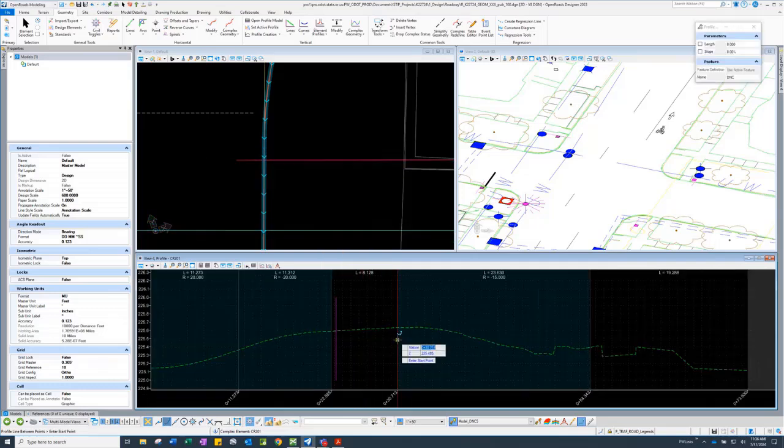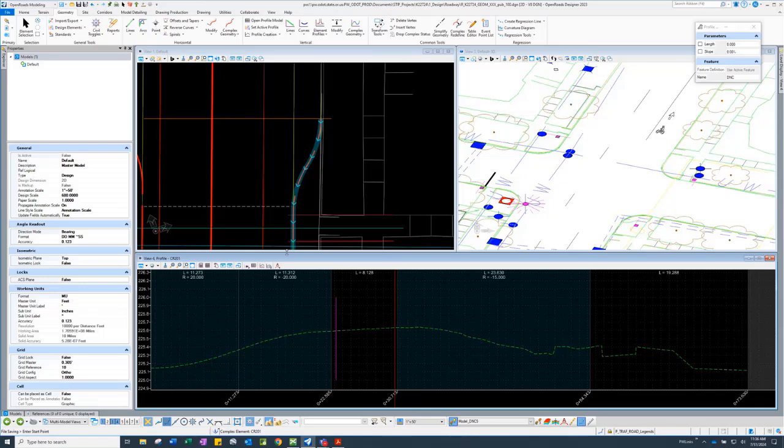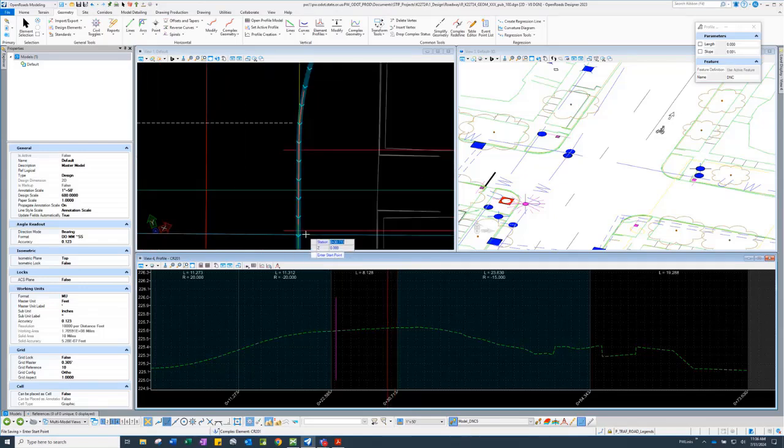What this does is it gives me a visual of where my ramp is, because when we're designing ramps, I have certain slope requirements. They cannot be more than 4.5% across certain intersection values, or 1.5%, etc. So this allows me to see in my profile where those limits are. It would be like somebody drawing where their right-of-way limits are in a profile. Correct. Same kind of idea.